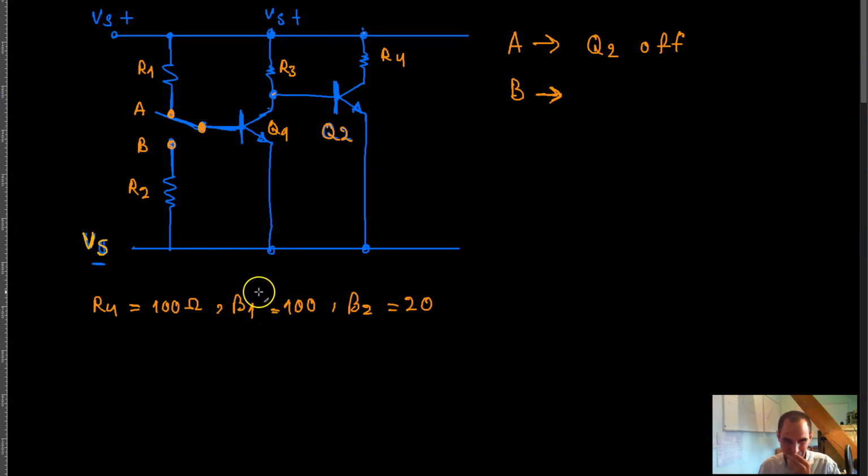Now I don't really know why that's important or why that works, but essentially it's something that you usually do when you want to ground the base of a transistor. You have to use a resistor whose value is somewhere between 20 kilo ohm to about 1 mega ohm. So you put a resistor between the base of the transistor and the ground, meaning that you don't ground it directly; you pass it through a resistor, and then the resistor goes to the ground, and for whatever reason it makes sure that the transistor never turns on. So that's basically what I know about this.